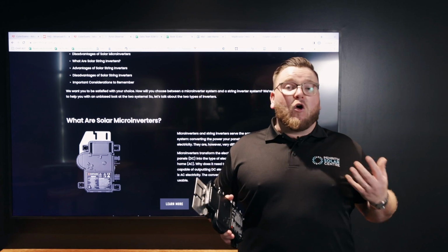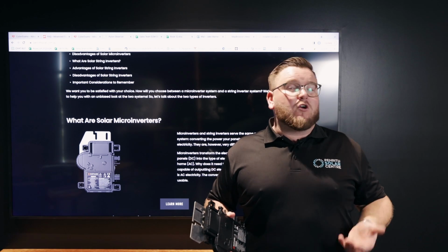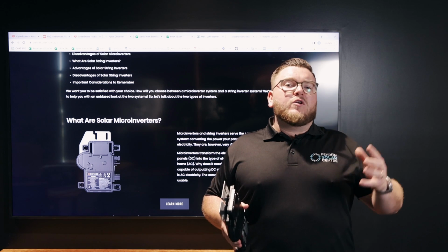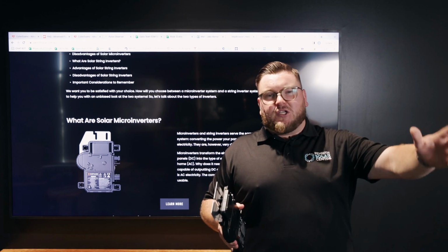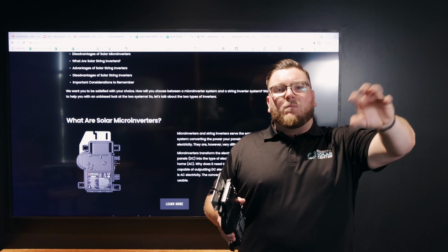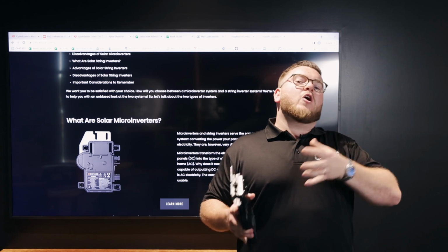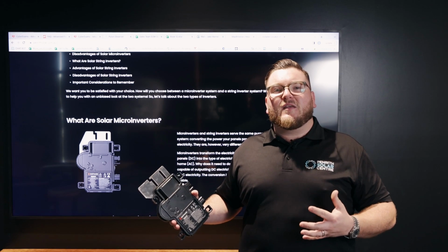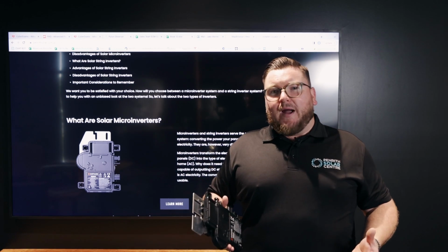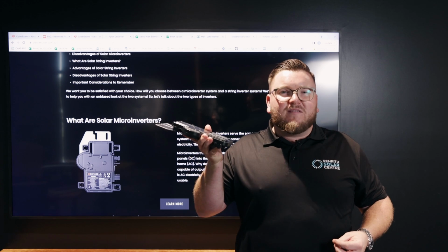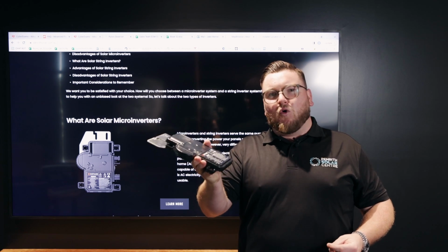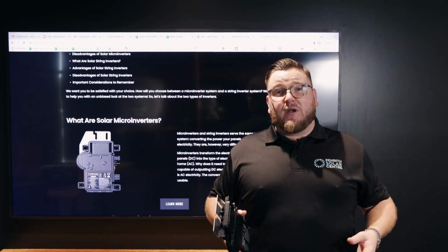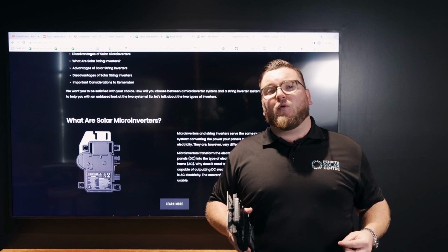Now you think about the origin in which your inverter is made. It could be China, it could be Europe, it could even be the USA. Now you think about the distance that it's traveled on a ship, well, ports to ship, to ports, to trucks, then loaded in the back of some installer's van or truck or ute, and then it's driven to your house. Now, that's a pretty bumpy ride. The potting mix ensures that not a single bit of stress or fracture is put on any of the electronics inside a microinverter. A string inverter, there are actually some pretty heavy components soldered to the PC boards of those string inverters.